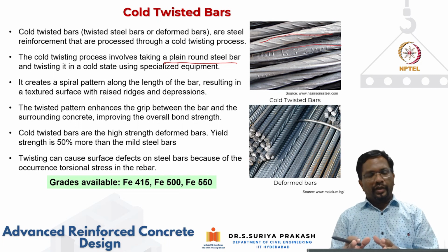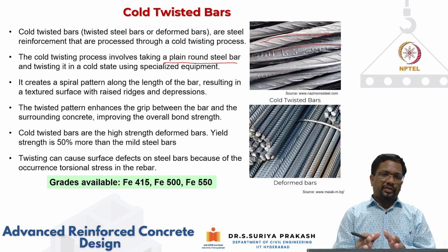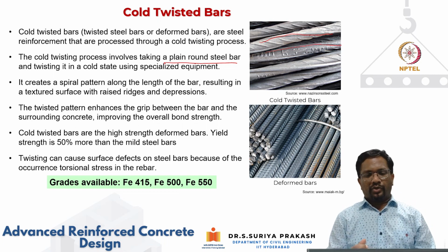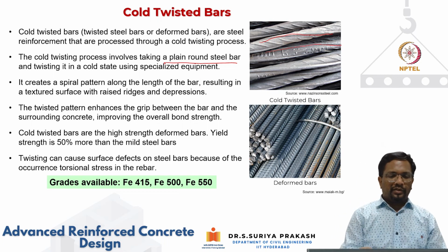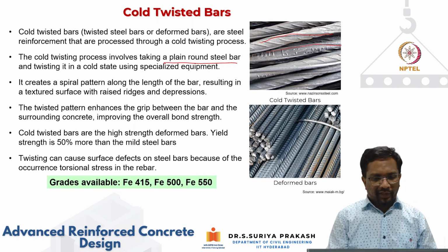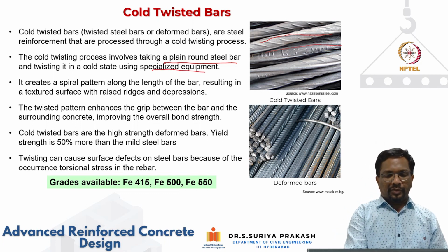Again, it is not really at a cold temperature. There is a temperature also applied, but the temperature is kept less than this recrystallization temperature, usually 400 to 600 degrees centigrade, using specialized equipment.